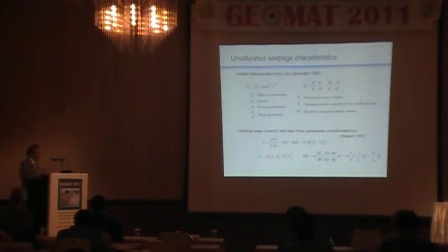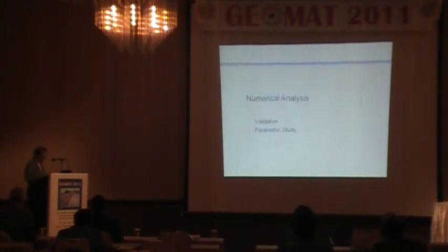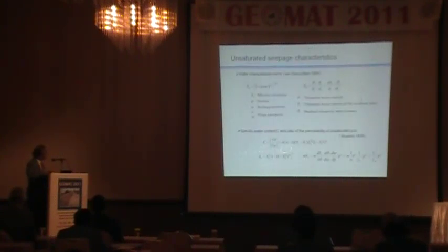Of course, we need the water characteristic curve as a constitutive model. In this case, we adopted a constitutive equation for the water saturation with the suction conditions. I also consider the effect of the saturation dependency of permeability.